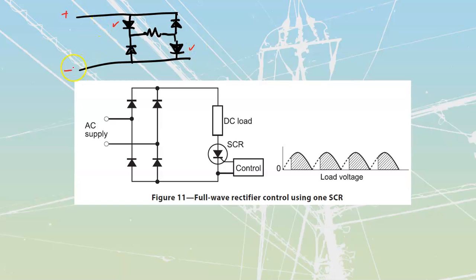So I would see that during this, the red cycle, I would be able to travel up through in that direction, and back out. And then if I change this over to the other alternation, positive, negative, like that, I would see that this one would be conducting, and this one would be conducting, negative to the cathode, positive to the anode.